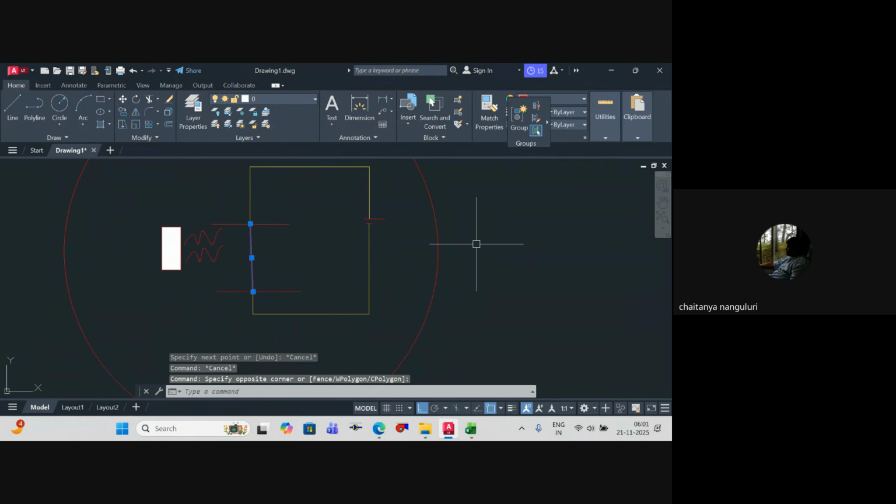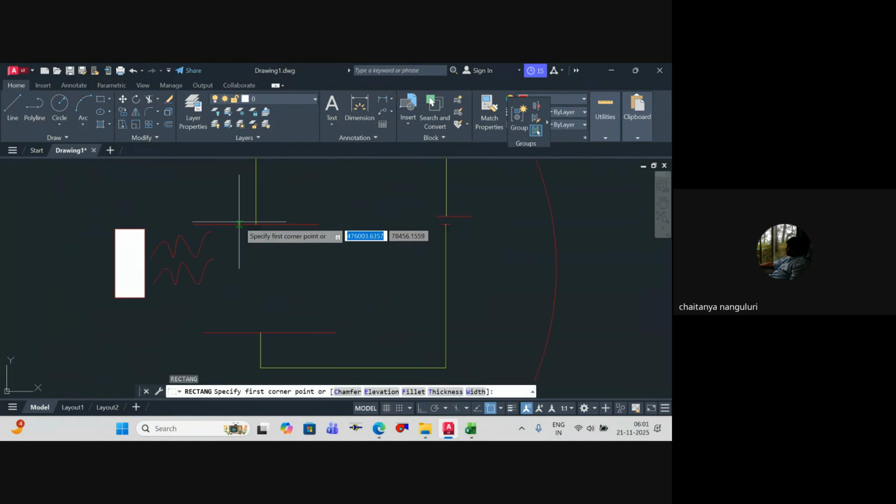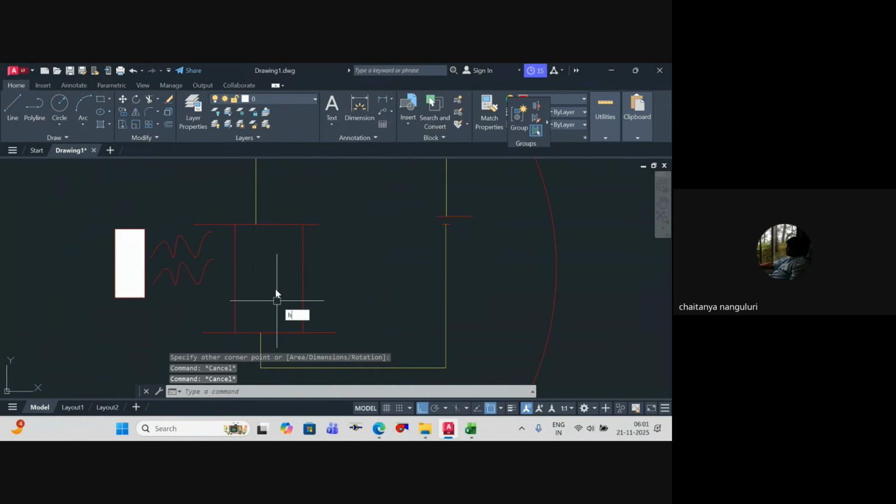So when the circuit is closed, it feels that there's no fire. But if fumes or anything enters this space, the alpha radiation doesn't have the power to ionize your fumes. Because of that, instead of a conductor, it will become a resistance, so electricity will not flow.